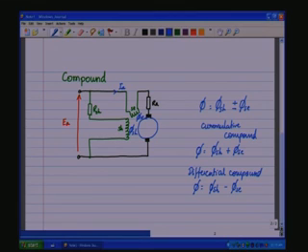So, there is a shunt excitation which is there. So, phi shunt is present inside the machine, and IA is beginning to grow. So, during initial conditions, the motor will act like a shunt motor.